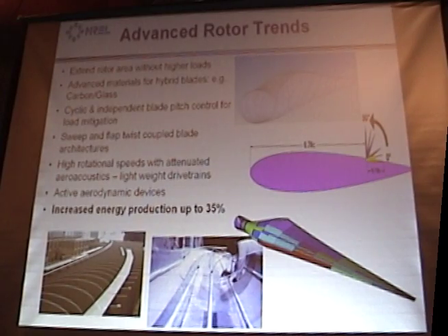When the blades are downwind, the wind passes through the tower and creates a vortex. And the blades, as they spin around, go through that vortex and create this thump. And it's an infrasonic noise below the threshold of hearing. And when you're standing next to a big machine that's operating like that, you can feel your whole chest resonating, and you don't even know what's causing it.